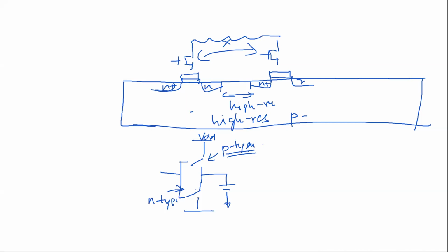So you mean that by adding the PMOS between the two NMOS, we want to isolate them? No, it's a P substrate. The entire chip is in one P substrate. It's like your PCB, right? When you're making an electronic device, that PCB is an insulator, an FR4 insulator, because you don't want circuits to talk with each other and be shorted. It's the same thing in IC. We can't use a PCB. We use a P-type material, and one of the reasons is that it's actually very resistive in nature, so that we are not shorting all devices.